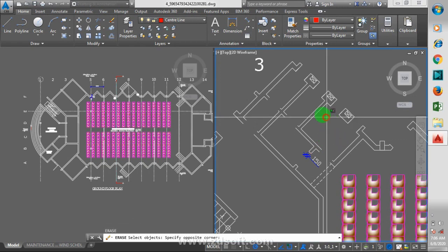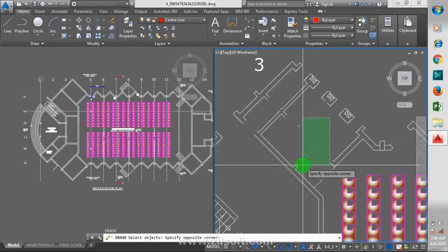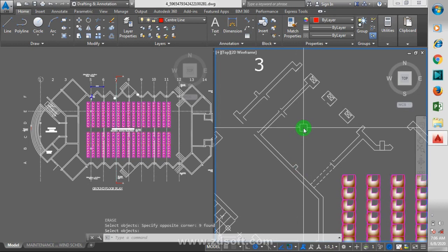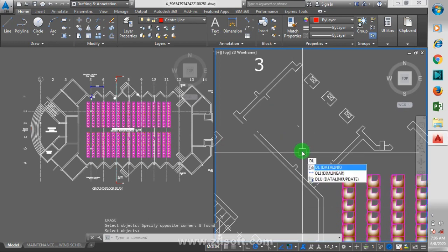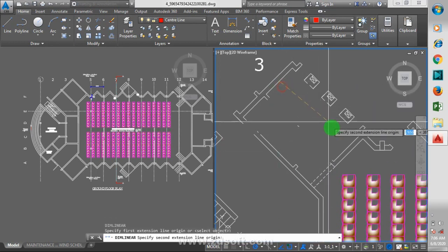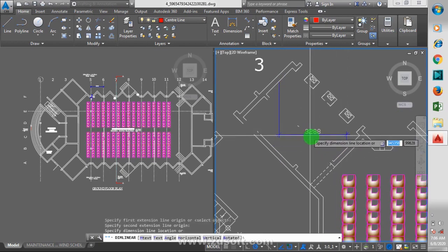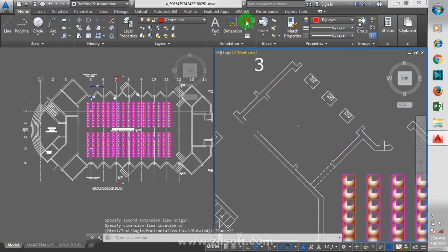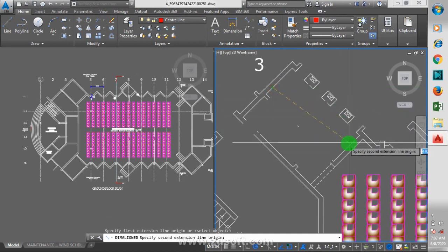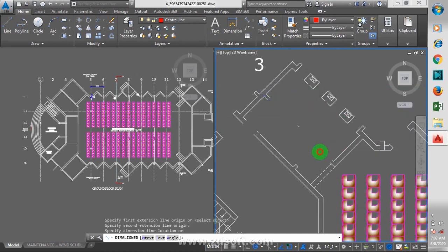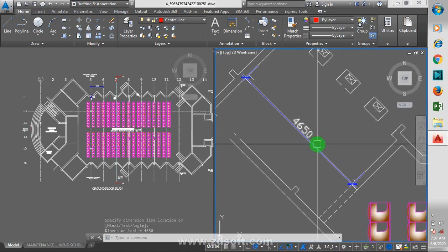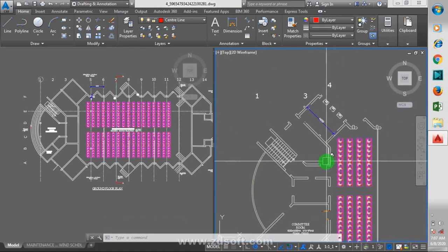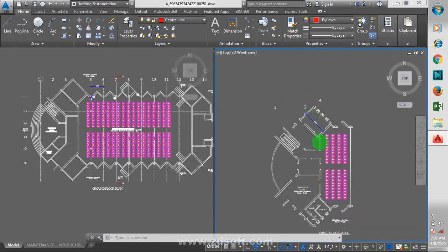So automatically this wall I'm going to delete, because the toilets and bedroom, your store, most times the walls are non-load bearing walls. Okay, so in that case such walls are actually deleted. And again, what actually affects this is when you check the span, maybe the span is not actually that large. You can take off that wall. Okay, you can see here now it's 4650. So I'm going to leave this at this.